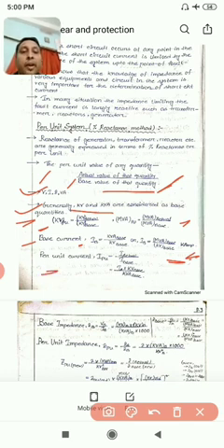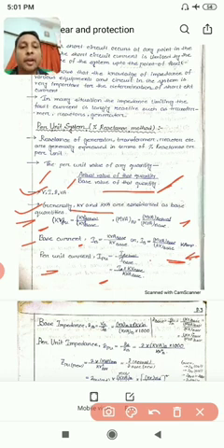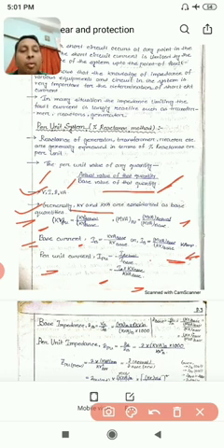So what will be the per unit current? Per unit is again actual current divided by base current. So I per unit is the actual current divided by the base current. You can see it from here: I am putting the value of base current here, kV base by kVA base. So what will be the unit of this IA? It will simply be in ampere.